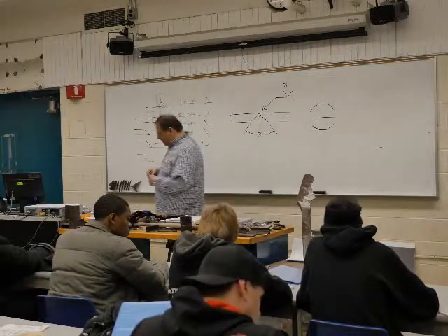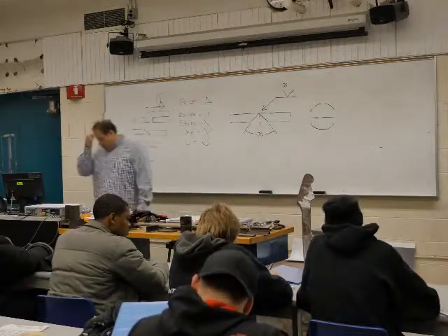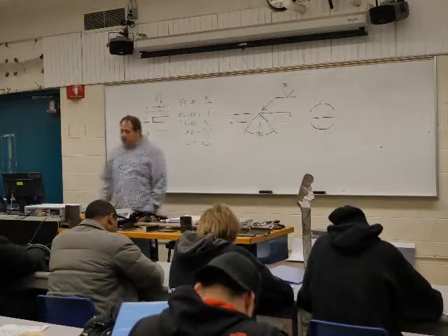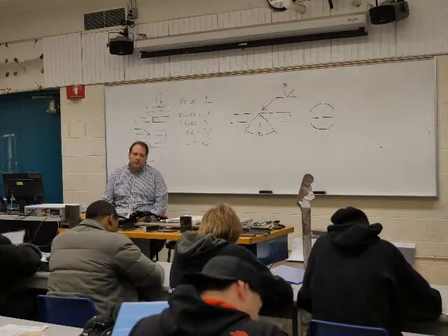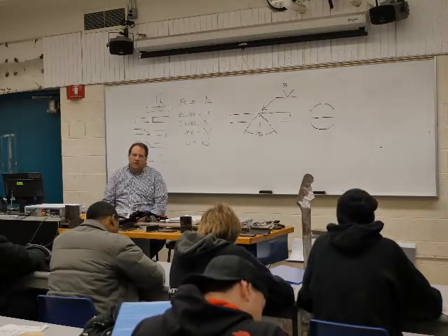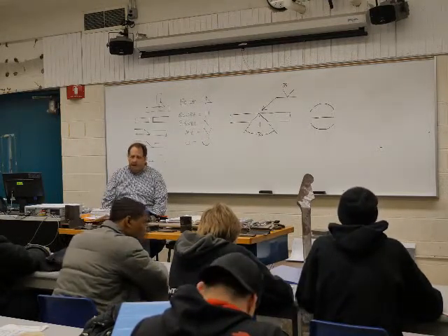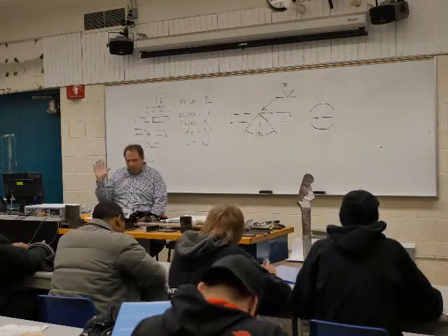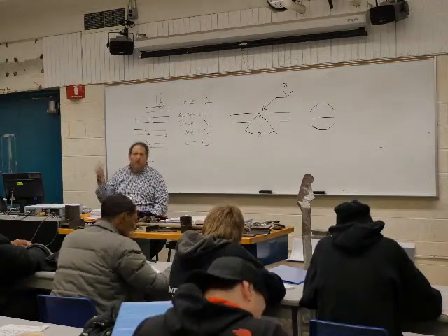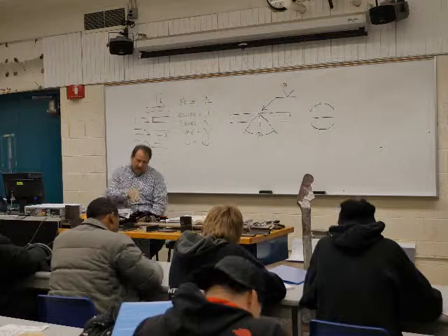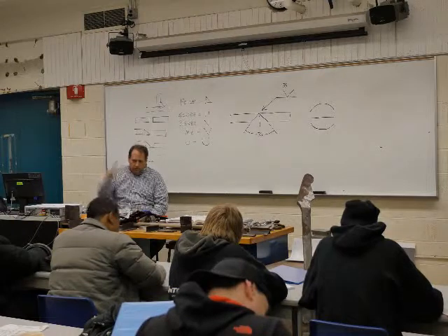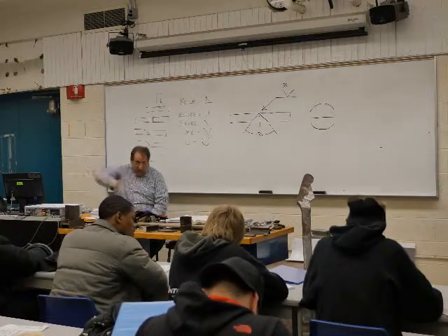Now, that comes into play a couple different ways. Sometimes, and this isn't too common, honestly, you might see a contour symbol say on a fillet weld, where because of some kind of tolerance or clearance that they need, they may tell you that that weld has to be concave. Just for reference for you guys, in case you're trying to remember which one, I always think of it in terms of concave caves in, and then flat is flat, and then convex is rounded.